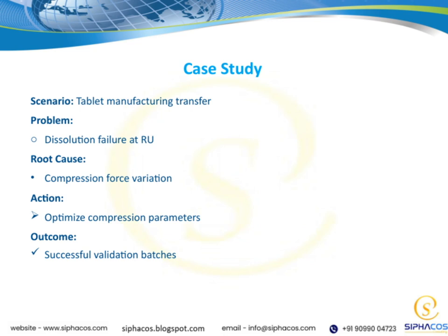The root cause identified was variation in the compression force during tablet production. This variation can cause inconsistencies in tablet density and integrity, leading to the dissolution issues we observed. To address this, the team focused on optimizing the compression parameters. By fine-tuning the compression force and ensuring consistency, we aim to eliminate the variability that was causing the problem.